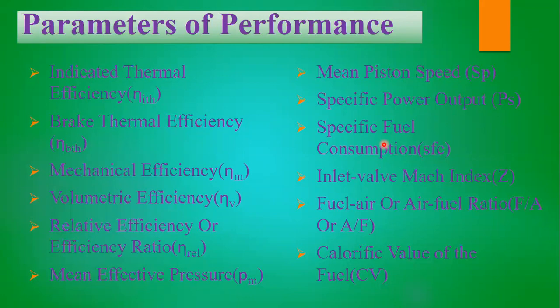Okay, whatever the energy produced, not all of it goes to the brake, connecting rod, crankshaft only. Some of the fuel consumed, some of the fuel power developed, is used to run some of the electrical devices within the automobile, right? So that's why the indicated specific fuel consumption and brake specific fuel consumption are going to be different here.